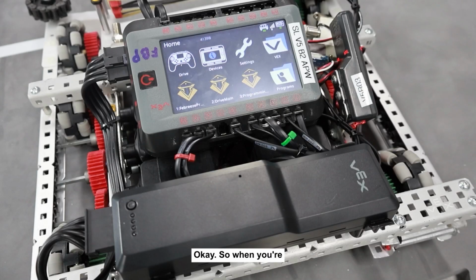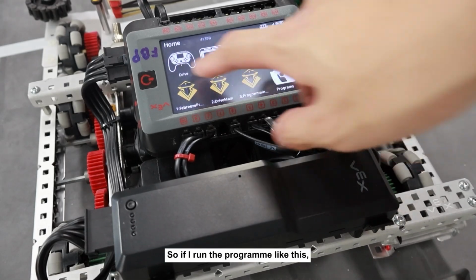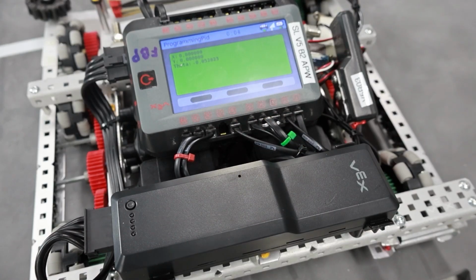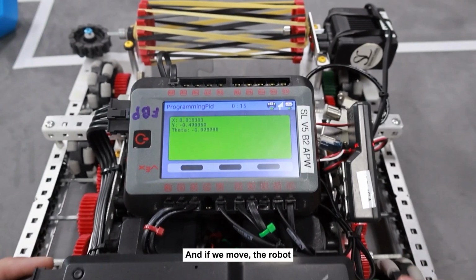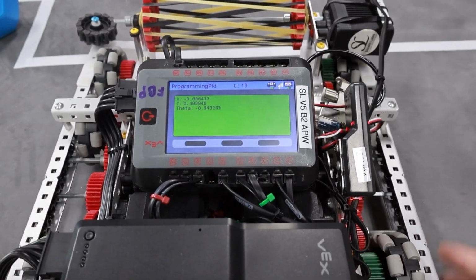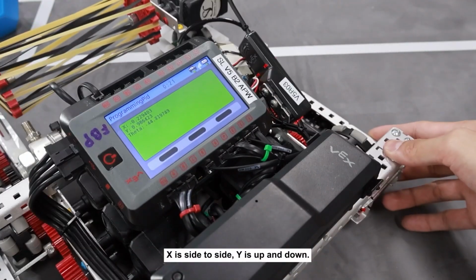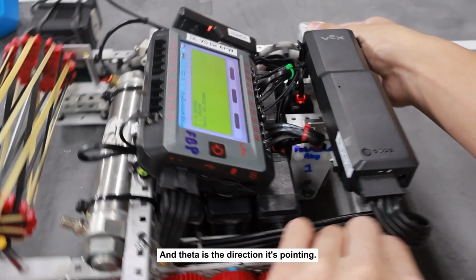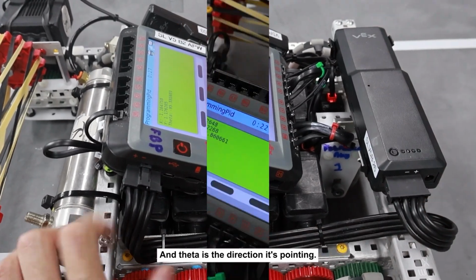Okay, so when you're programming your autonomous, since we have the odometry and the IMU installed, it'll actually output the coordinates to the screen. If I run the program like this, you can see that after a while, the coordinates actually show up on screen. If we move the robot, we'll be able to see it change. You can see that X is side to side, Y is up and down, and theta is the direction it's pointing.